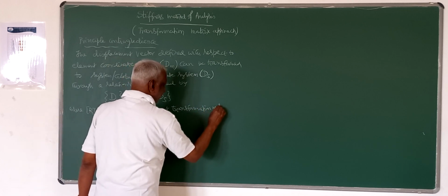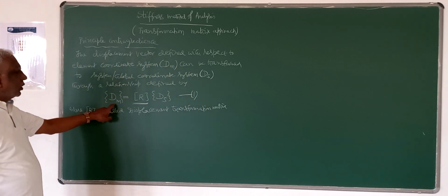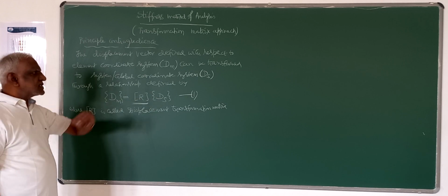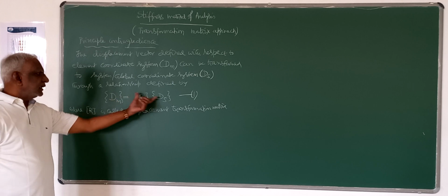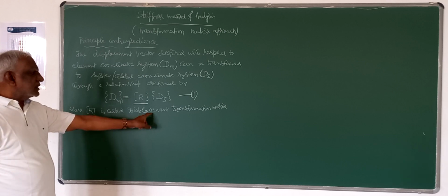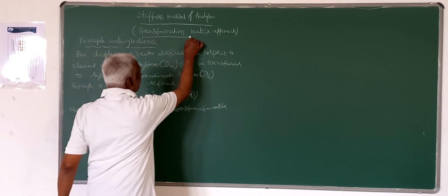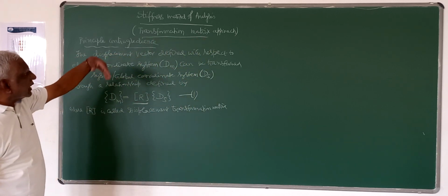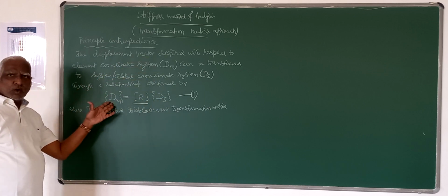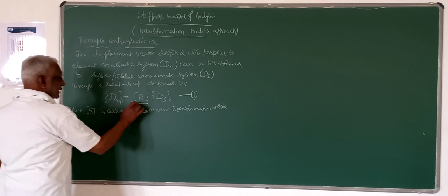The displacement transformation matrix is the relationship between this local coordinate displacement vector and the global coordinate system vector. Because this is the transformation matrix approach we are doing, we have to transform whatever equations we derive for the local coordinate system to the global coordinate system like this.